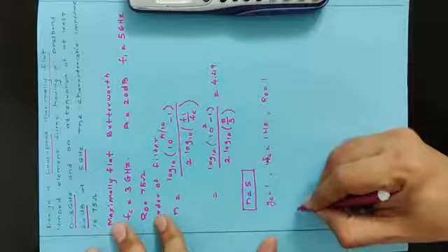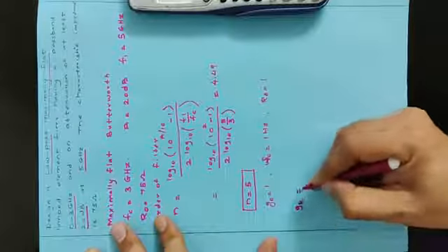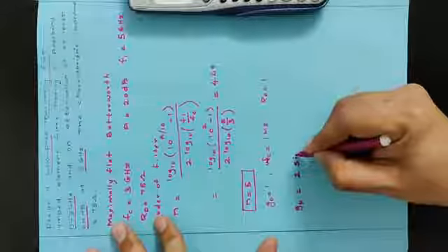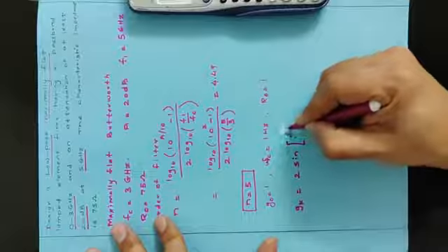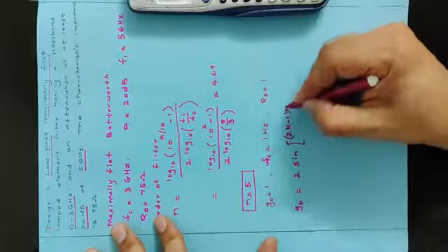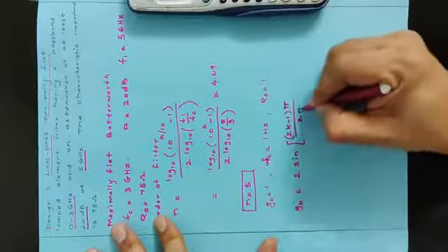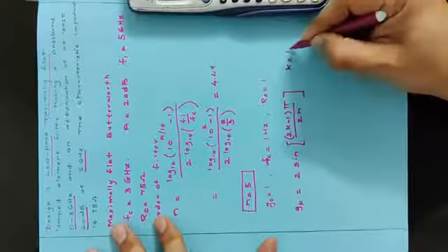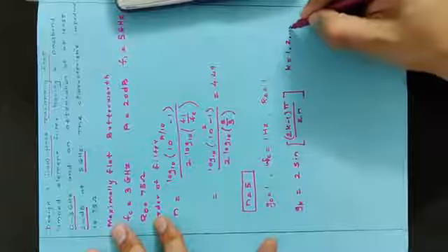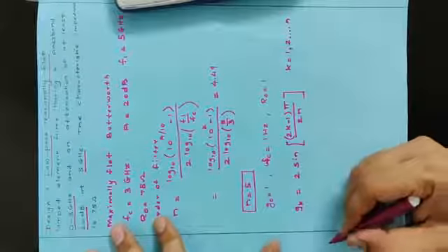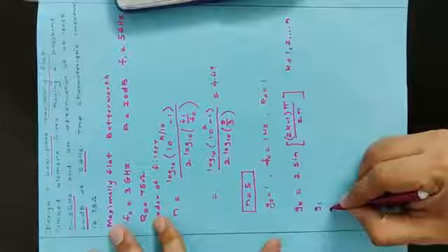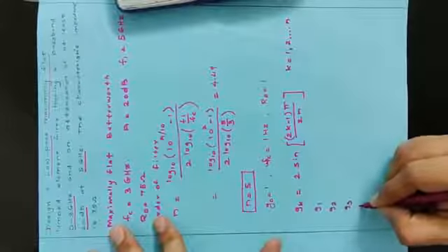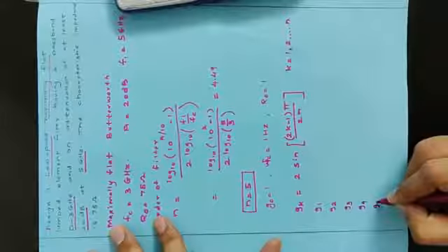So the coefficients are given as Gk, which is equal to twice sine of (2k minus 1) pi by 2n, where k is running from 1 up to order n. So we will have G1, G2, G3, G4 and G5.